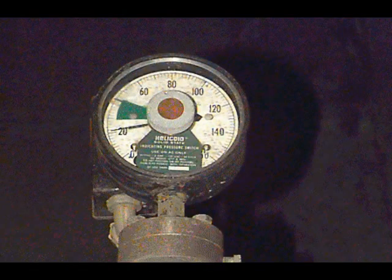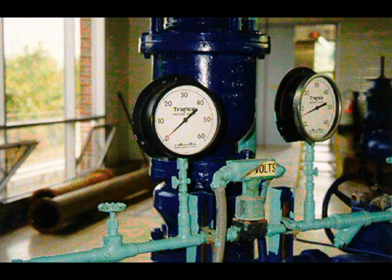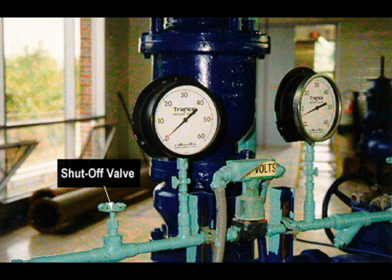Accurate pressure readings provide important information about what is happening in the system. Conventional pressure and vacuum gauges are not usually operable for any long period of time in a sludge pumping system. The gauge passageways clog with hardened sludge, and the gauges fail because of high pressure surges. If conventional gauges are used, it is recommended that shutoff valves be installed at the gauge inlet to be opened only when readings are being recorded.